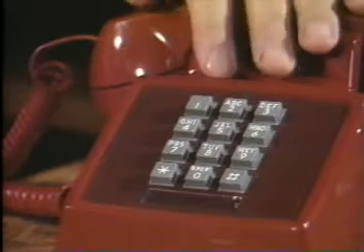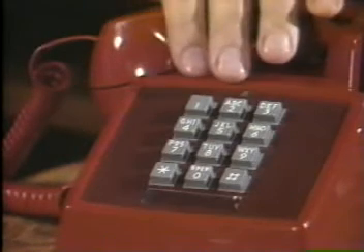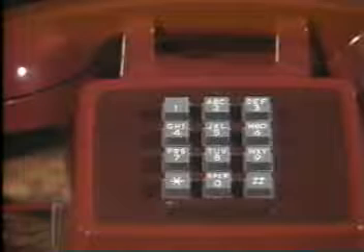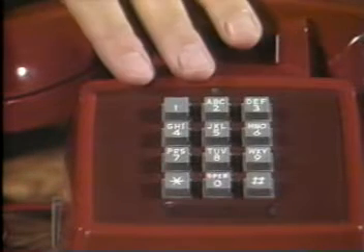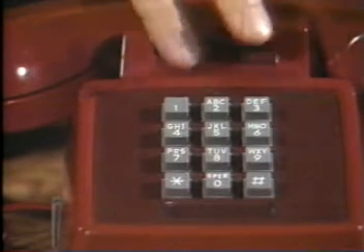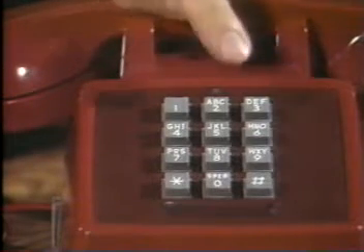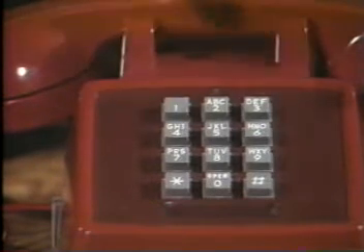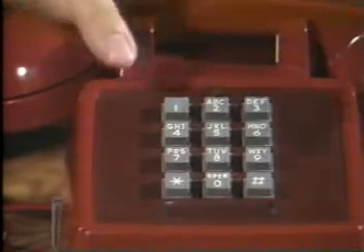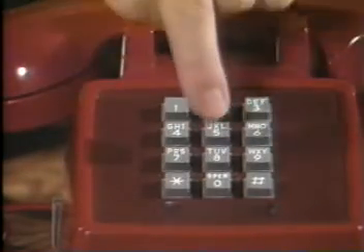Other types of telephone sets use dual-tone multi-frequency or DTMF dialing to generate and send telephone numbers. DTMF dialing can only be used, however, if the central office is equipped with a DTMF receiver. Telephone sets employing DTMF dialing use a keypad rather than a rotary dial. The keypad generally has 12 keys which represent the digits 1 through 0 and the symbols star and pound.